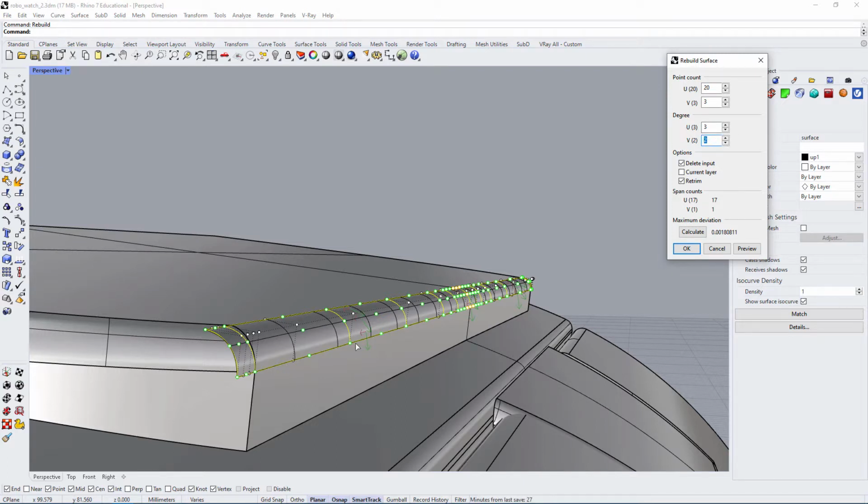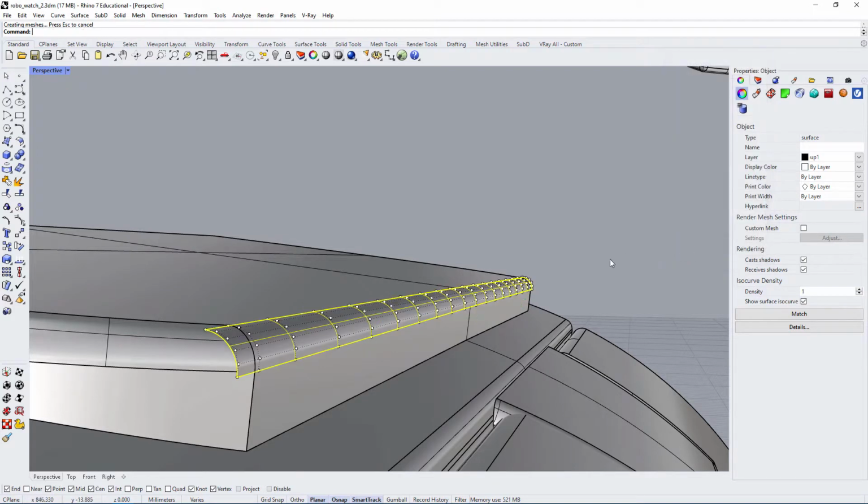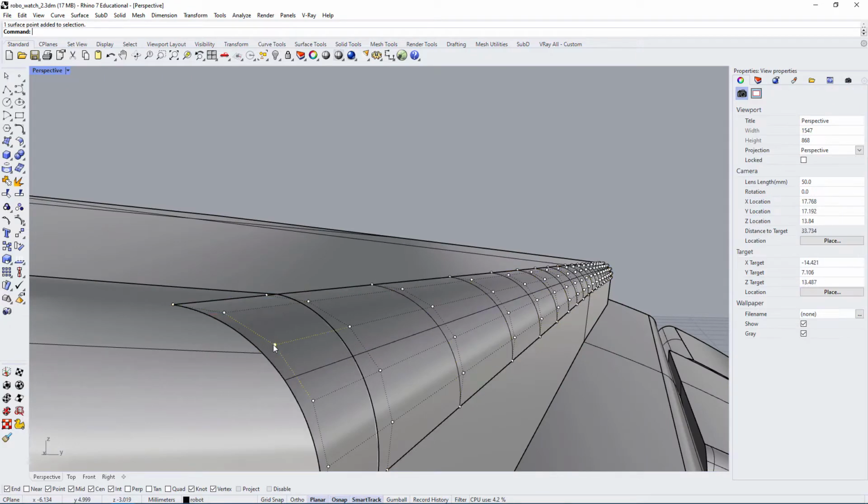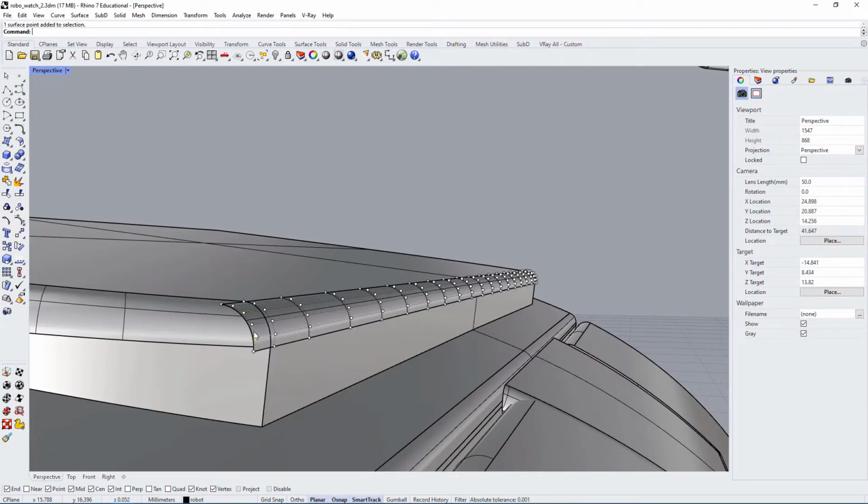Like I said, a fillet surface is a transitional, but for this project, we want to see something that's a little smoother, that has a better transition. So usually 5 is a good number, so we'll do 5, which automatically changes the upper number, which is a point count. So with 6 vertices, with 6 control points, you'll see that you can have these two sets of points, and they can be aligned.